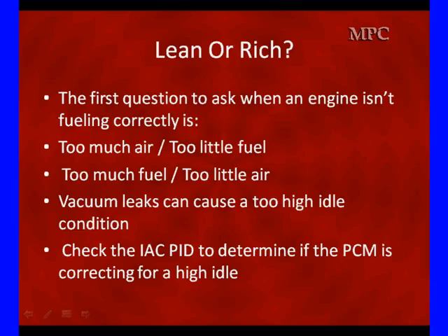The first question to ask when the engine isn't fueling correctly: do I have too much air or too little fuel? What causes too much air? I could have a vacuum leak after the mass airflow. Do I have too much fuel and too little air? Do I have a miscalculation where I'm delivering more fuel than I need for the air I've got?